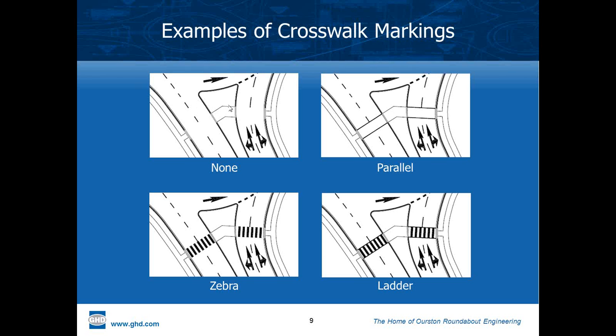Now, the idea of not providing any crosswalk accommodation, I wouldn't oppose that. In Europe, and particularly in England, they have a sort of needs test, which is a function of the pedestrian volume multiplied by the vehicular volume squared, so raised to the power of 2. And that is pedestrian PV squared, as they call it. They tabulated certain thresholds where no crosswalk is required, where a crosswalk without markings is required, and then moving up to a full signalized crosswalk is required.